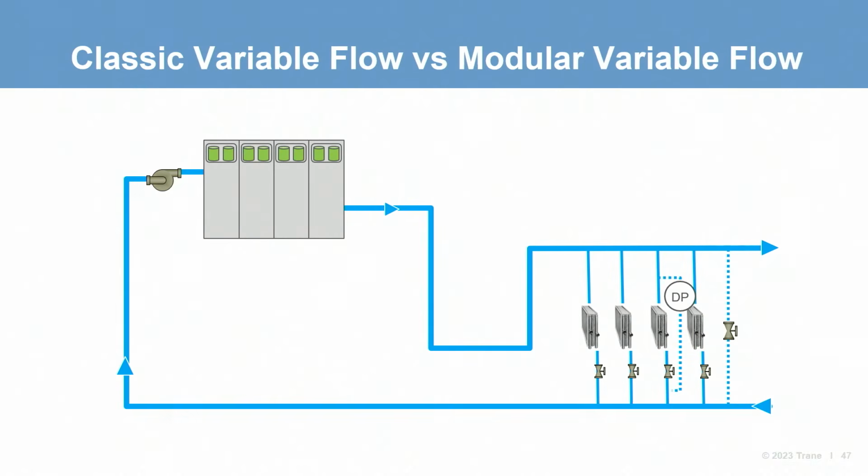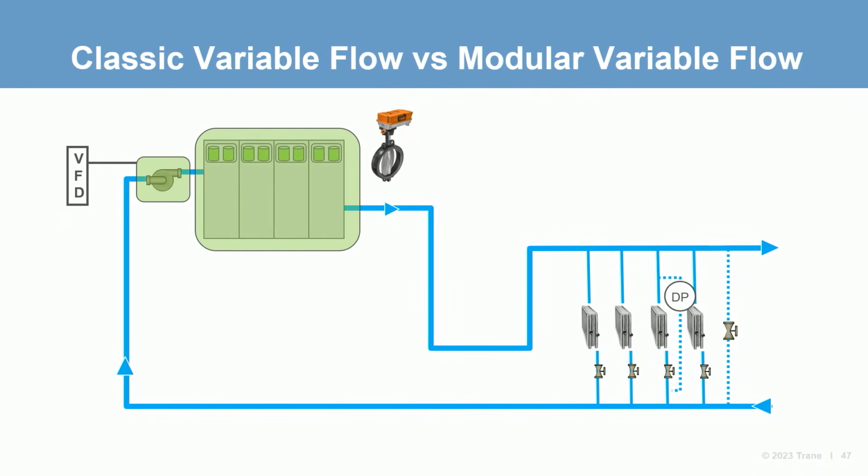All right, now let's put the components we defined into our system with a modular chiller. Here we see a single modular chiller in a variable primary flow system that appears a little different from our previous system. Let's walk through this system and find out what is the same and what is different and why. First, which is the same as the previous system, we have pumps fitted with VFDs. There are multiple ways these pumps can be controlled, and we will explore some of those strategies towards the end of this section. Second is that the modular chiller is configured with automatic isolation valves.